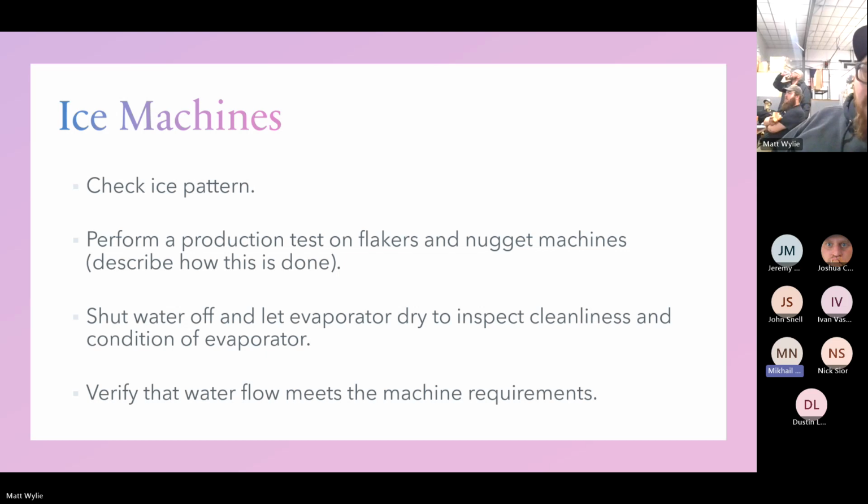Joel and I recently did a walk-in cooler, and it had a TXV on it that was 30 years old, and it was for an R22 system. One thing I learned was that you can get all the information off the head of the TXV. We substituted with R422B, but it was still compatible with the R22 refrigerant. It was cool because you couldn't find that TXV anywhere, but we had a supply shop make one for us, and all we had was whatever was on the head of the TXV, and it worked.